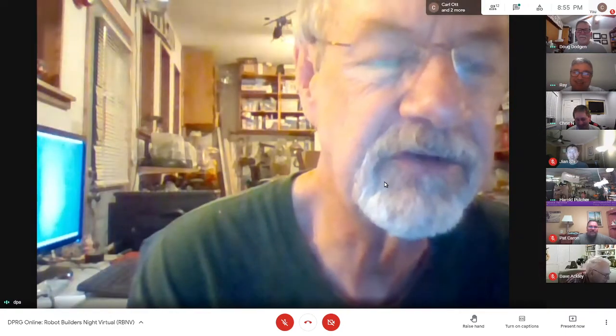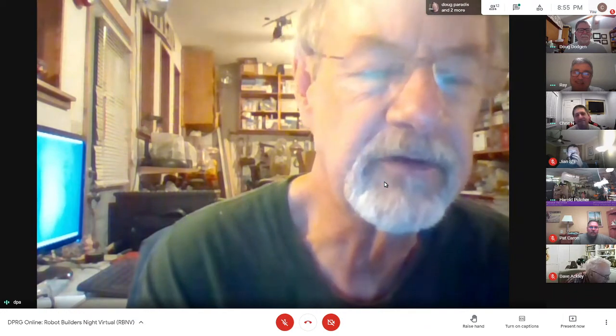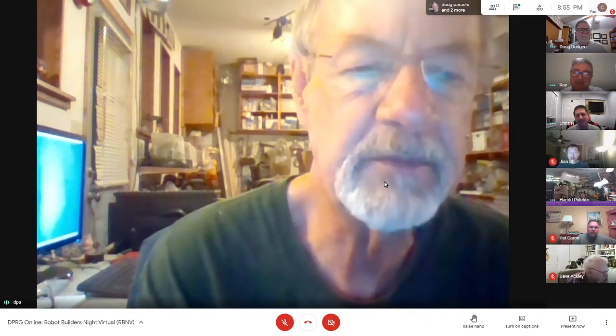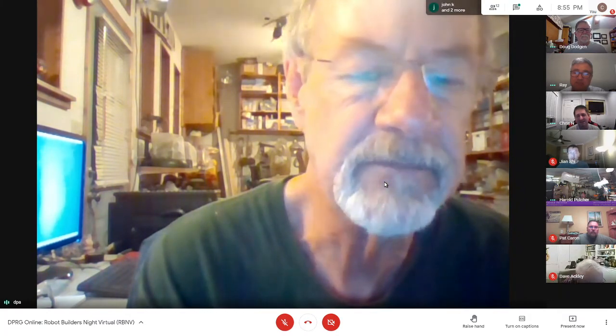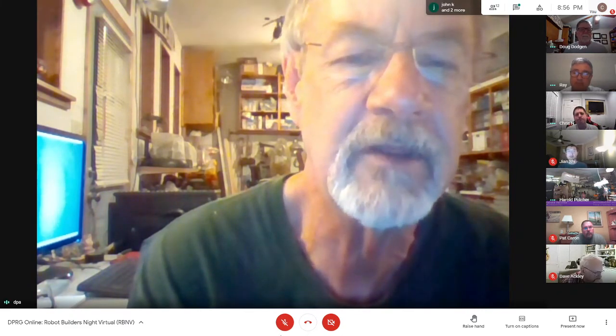Also, I think there's a question as to, if you're actually going to drive a robot with a video feedback link, what's the acceptable latency such that you don't run into the walls? This is kind of ancient stuff now, but back in the before time, I worked at the electronic music lab at the University of North Texas, and we did a bunch of tests to see what latency musicians would put up with between the time they pushed a button and the time they heard the sound. Sitting there at a keyboard playing, it was on the order of 5 milliseconds. And if it got longer than that, they began to complain about it. I would imagine the same would be true if you were, say, driving a race car.